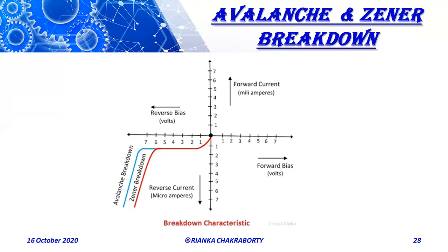On the other hand, avalanche breakdown takes place in a junction having a wide depletion region. With the rise of temperature, the crystal ions vibrate with a greater amplitude, increasing the possibility of collisions of the carriers and the crystal ions. The carriers thus have less opportunity to pick up enough energy between collisions to trigger the avalanche process. That's why we can say that the temperature coefficient of the avalanche breakdown voltage is positive. So these are the differences between avalanche breakdown and Zener breakdown.